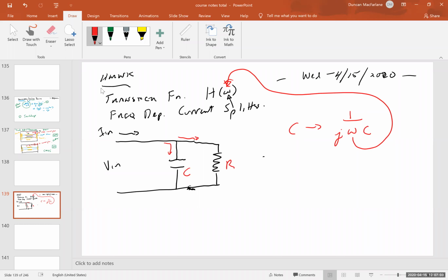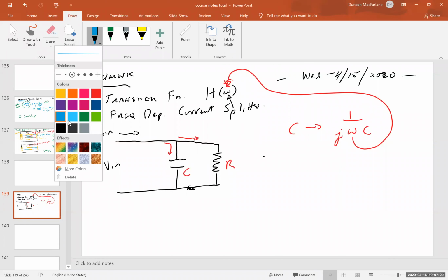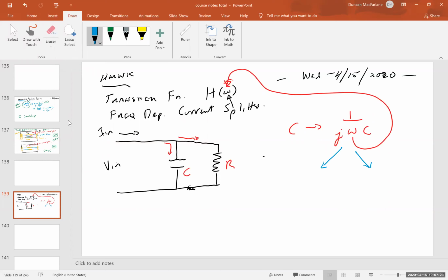And so the first thing to do is to say, okay, what are my two limits of this impedance? Just let's look at the circuit intuitively, and let's try to understand it quantitatively. And the first one is the DC component at omega equals 0. And in this case, that 1 over 0 goes to infinity. So the impedance of the capacitor is an open circuit.